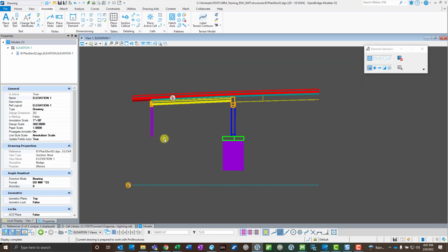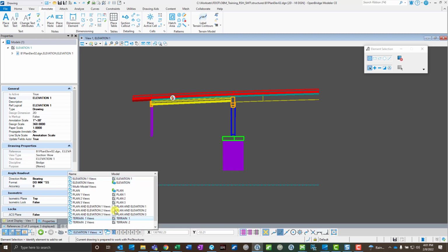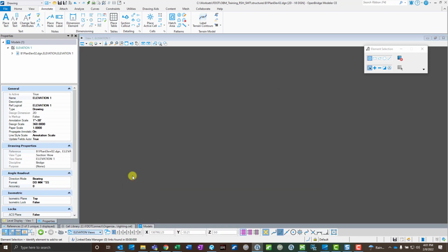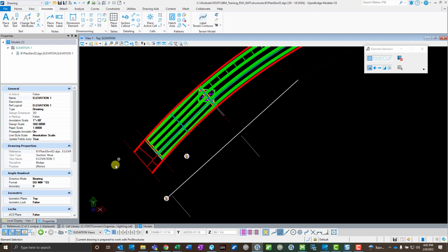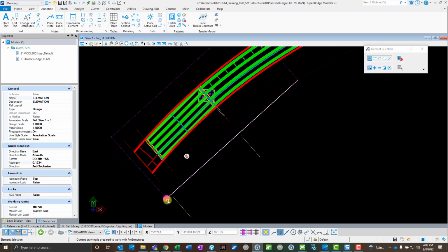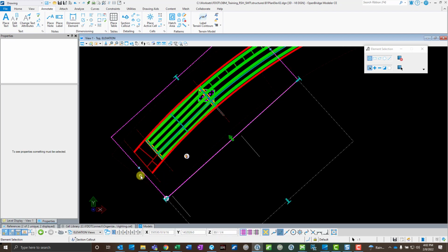And then that is going to be lined up with our plan view, so that looks good. But let's go real quick and adjust this section callout tool we did, because we do want it to actually capture the full extents of the named boundary. And we had to snap down here as a starting point. But let's go ahead and click on that